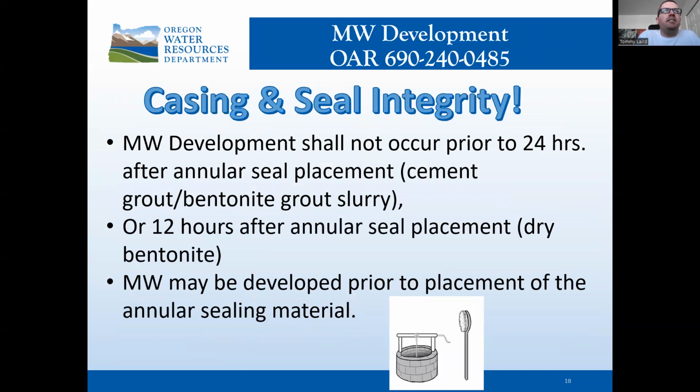So we are now going to move on to casing and seal integrity, as in OAR 690-240-0485. Monitoring well development shall not occur prior to 24 hours after the annular seal placement for cement grout or bentonite grout slurries, or 12 hours after annular seal placement for dry bentonite. The monitoring well may be developed prior to the placement of the annular sealing material.